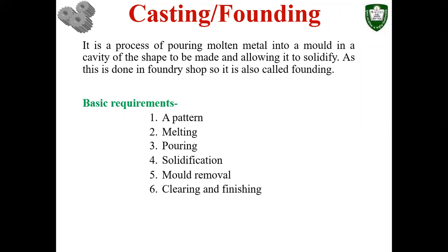And also in the case of plastic parts, if you want to do casting on plastic parts, then you also need to be really careful where the gates will be, how you introduce the molten material into the cavity. So you need to have a pouring system, how the molten material will flow into the cavity. And the fourth one is the solidification.